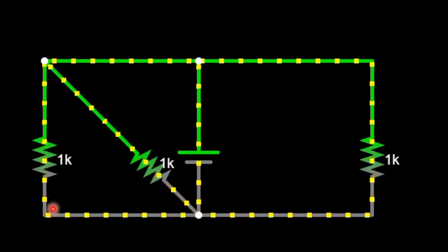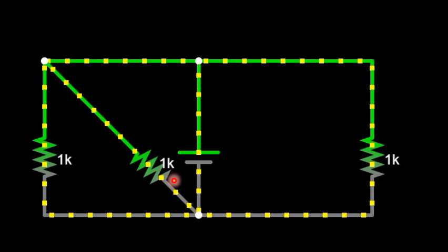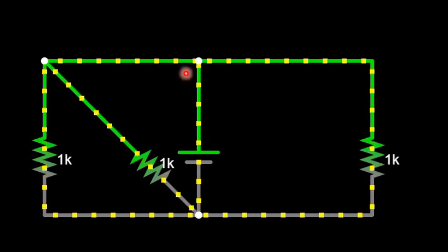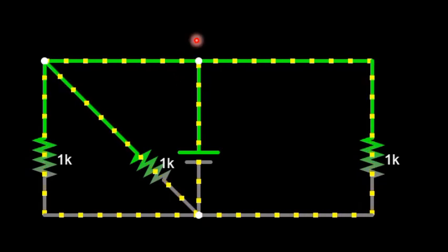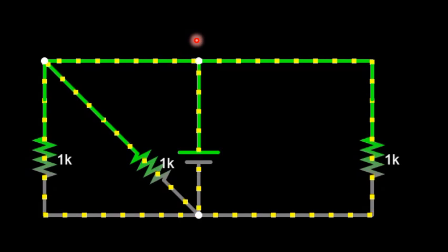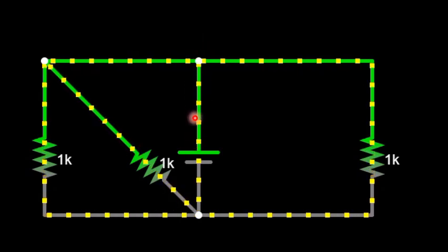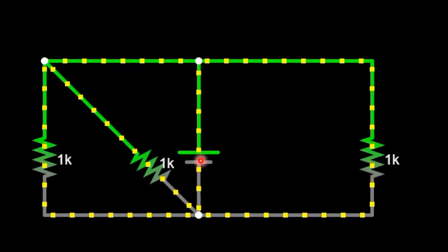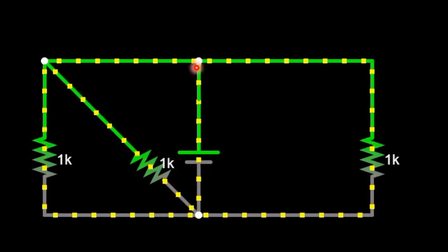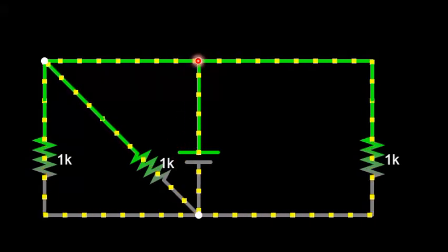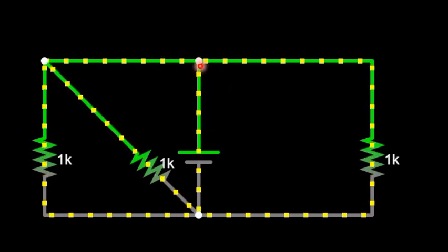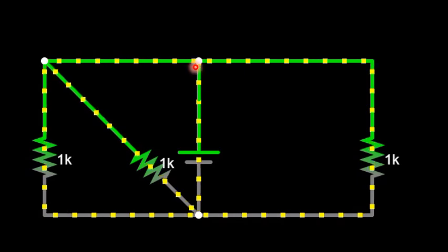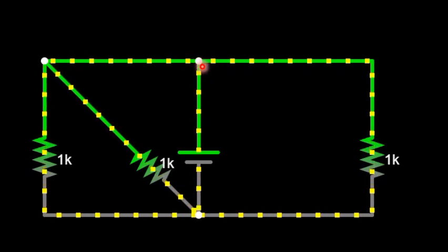One trick I also want to give you to easily detect whether resistors are in parallel or not is, whenever there's a current flowing from the source, let's say it starts from here, when it gets to this node, ask yourself, does it have a choice or no choice? If it has a choice of direction, that tells you there's a parallel somewhere.